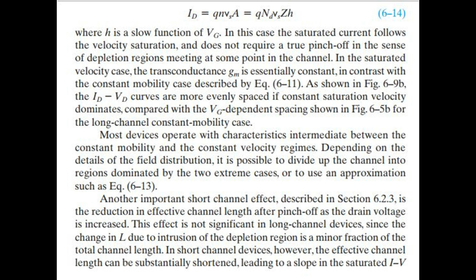Most devices operate with characteristics intermediate between the constant mobility and the constant velocity regimes. Depending on the details of the field distribution, it is possible to divide up the channel into regions dominated by the two extreme cases, or to use an approximation such as EQ. 6.13. Another important short channel effect, described in section 6.2.3, is the reduction in effective channel length after pinch-off as the drain voltage is increased.